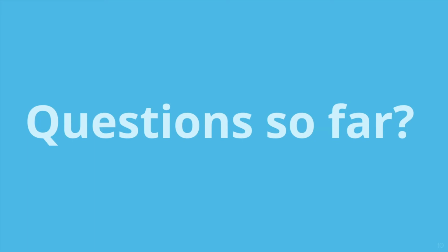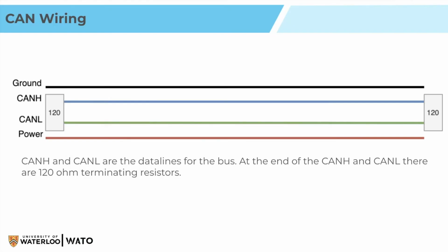Yeah. Cool. Going back to the CAN high and CAN low bus lanes, we have the terminating resistors on either side, but you said that it can be used as pull up or pull down resistors. In the context of CAN, our signal gets transferred by the difference between CAN high and CAN low. So how does the resistor become pull up or pull down?